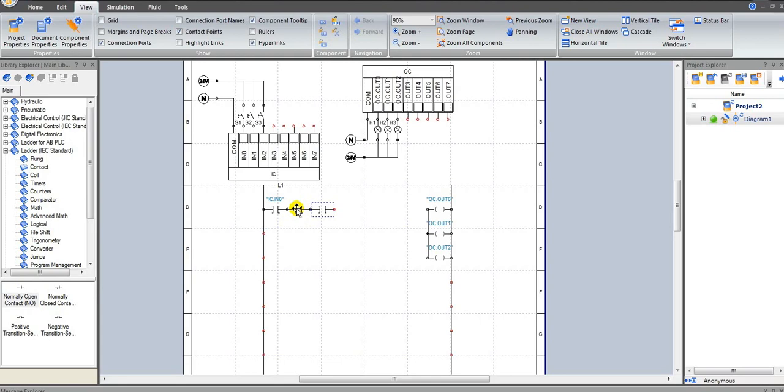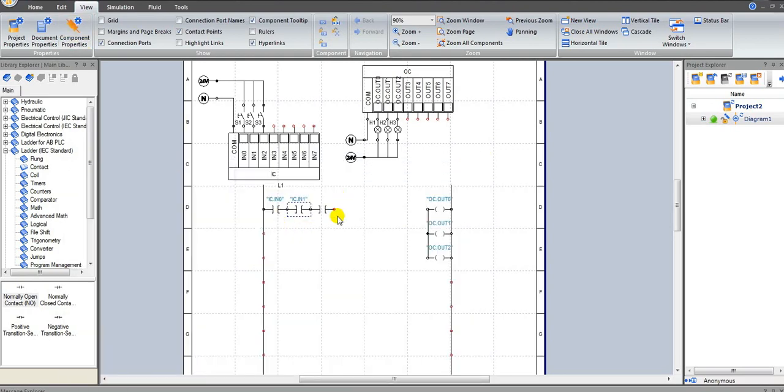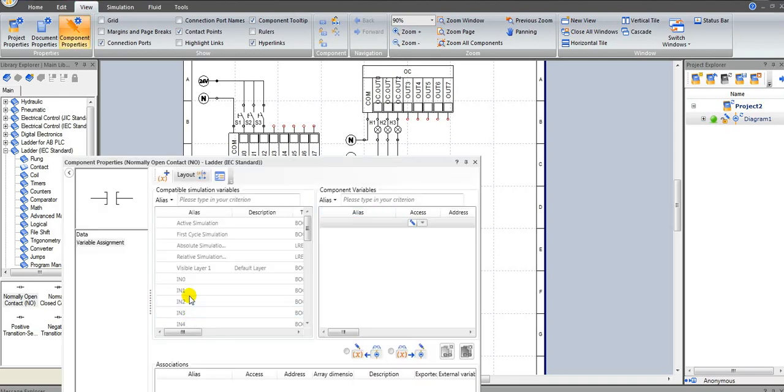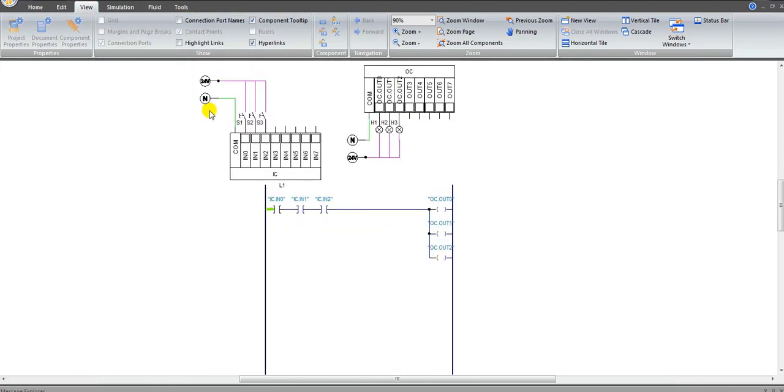We now change the PLC program. We will let the three bulbs light when all of the switches are closed. As you see, the bulbs light only when all of the switches are closed. This is what we call the serial or the AND function.